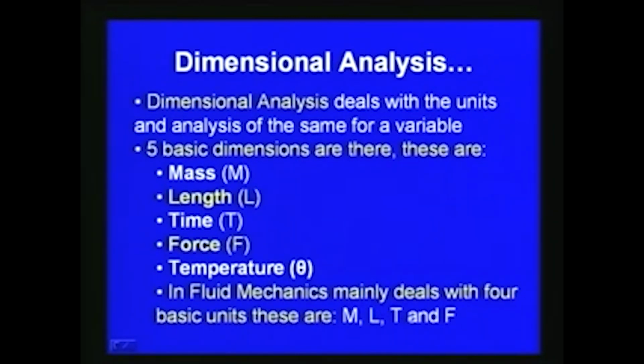So, mass, length, time and force are the 4 basic units we generally deal with in fluid mechanics problems. Between mass and force, depending upon the problem, sometimes we may use mass and sometimes we may use force. So, generally we can put it into a system of 3 basic dimensions, either mass, length and time, or force, length and time, depending upon the problem. These are the fundamental dimensions, and based upon these fundamental dimensions we will generally be doing the dimensional analysis.